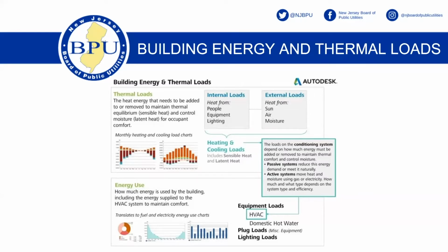So what do you do in a case like that? Well, you look and see, why did the engineers have this high ventilation rate to begin with? Well, there were fume hoods in the building. Okay. So now you want to get Phoenix controls on your fume hood so that when the sash is in a certain position, it lowers the ventilation rate. You get occupancy sensors, you get CO2 monitors, you get all these different wonderful technologies we now have to reduce the demand.